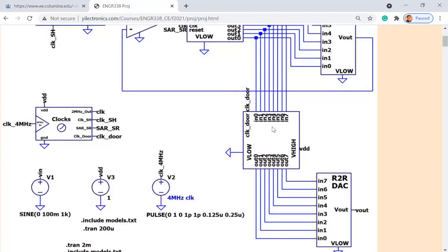There are several types of shift registers. Remember, if you have learned that in logic, you definitely learned it, but probably forgot about it, which is fine. Just looking at the structure, is it serial in, parallel out, or parallel in, parallel out, or parallel in, serial out? Yeah, parallel in, parallel out. You have 8 bits for the input and 8 bits for the output. So the 8-bit register is not doing anything but acting as a latch, or like a switch. Whenever you want to send the signal out to the DAC, you just turn it on. It's parallel in, parallel out.